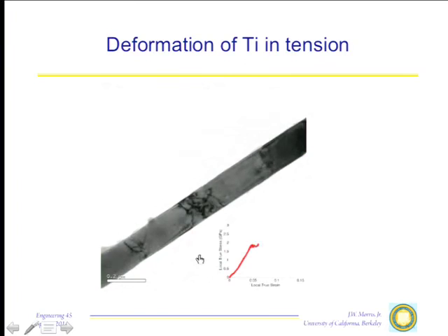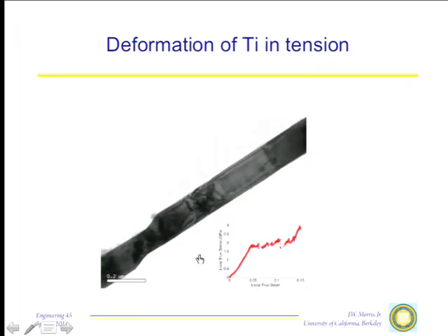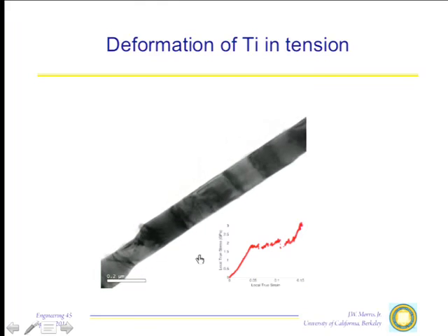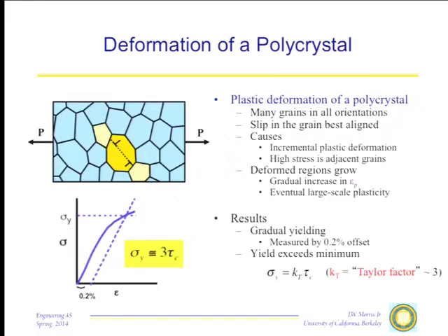Did you see a dislocation flipping along that 45-degree line? It happens so fast that you can sort of see it flash by in the picture. The dislocations go along that 45-degree slip line and leave this deformation, which causes the sample to get longer. And that's basically what's happening in plastic deformation, of course, on a much broader scale.